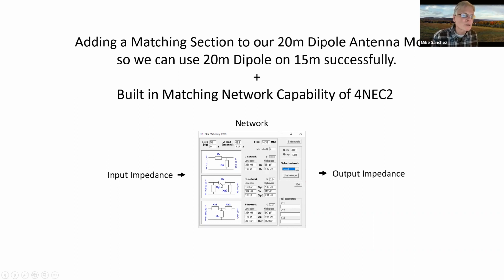Now, coming up with those coefficients would require you to use MATLAB or something and invert the matrix and solve it. But when you click one of these and then run it, you get the result and all 6 coefficients show up here. And you can just copy those into the network card and then use them.